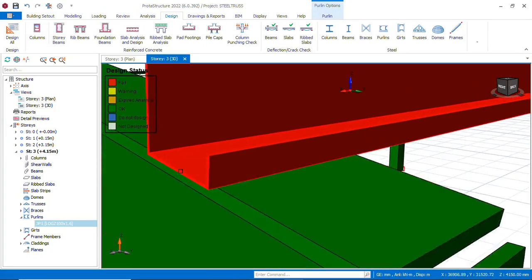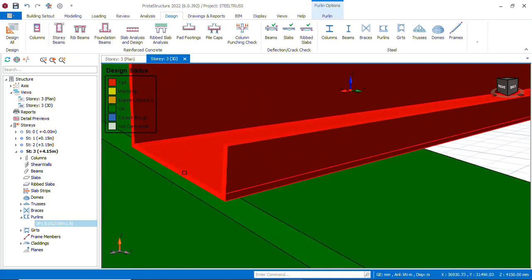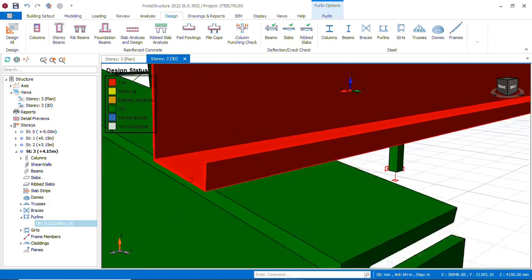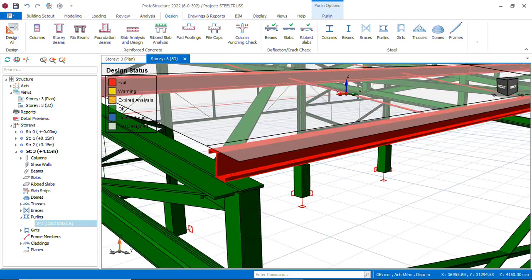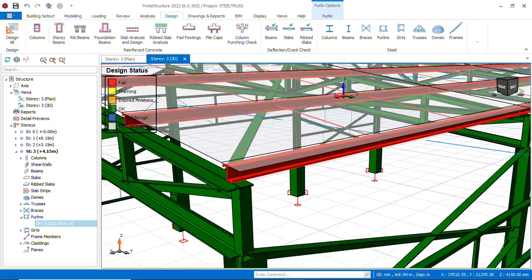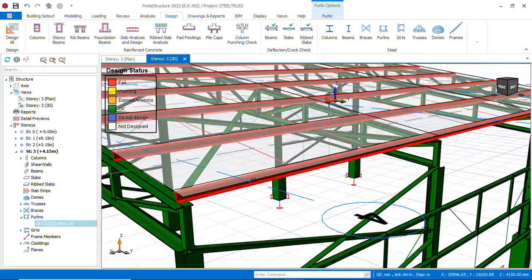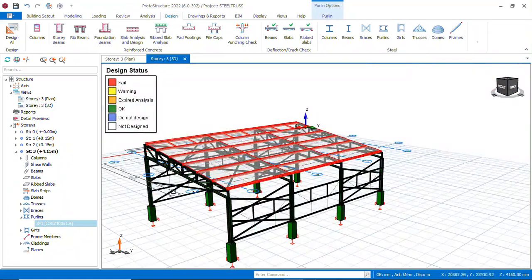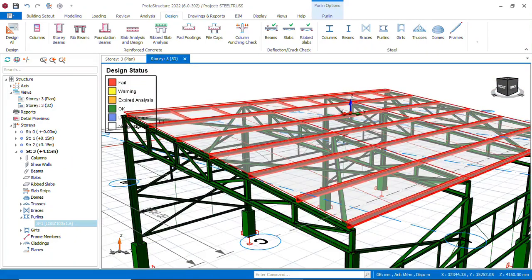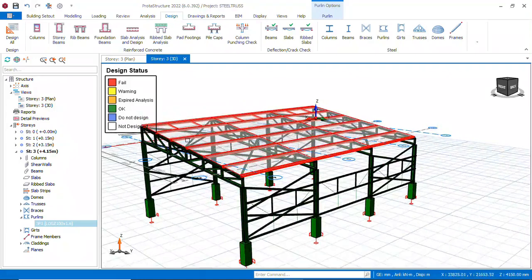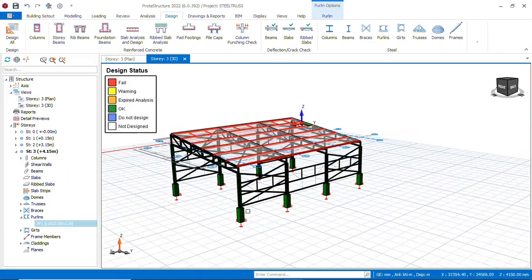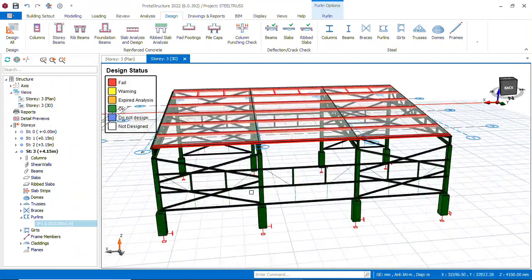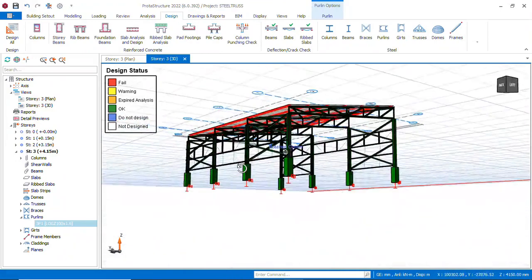It was 1.6, we increase it to 2, or 2.6. Then you run your analysis, or you delete this, put a bigger section and rerun the analysis all through. So that is just what you do.